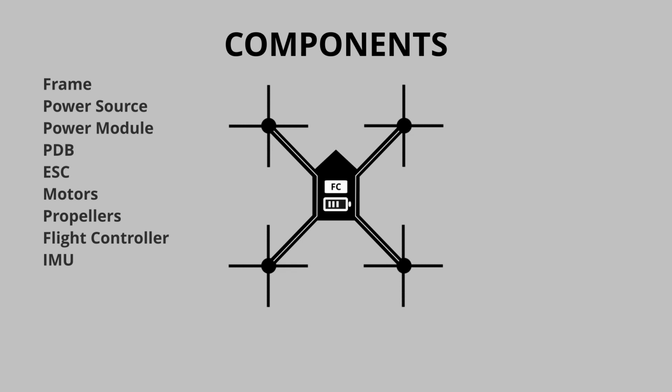The flight controller also takes input from other sensors and also takes commands from the entity that controls the drone. It could be an operator. So when the operator tells the drone go forward, it uses both that command with the speed that is expected and also the input from the sensors, making sure that the drone moves forward in a stable manner.